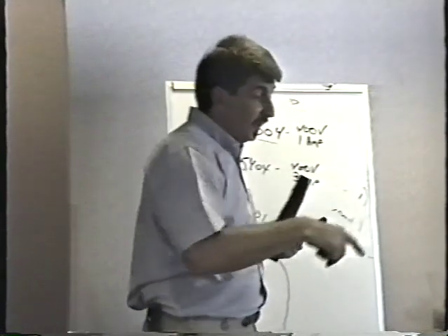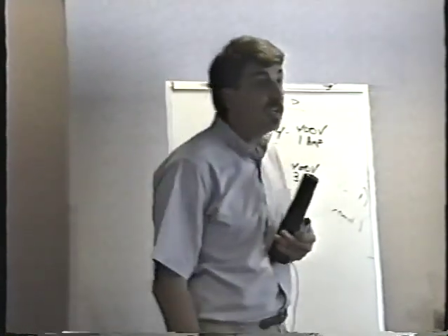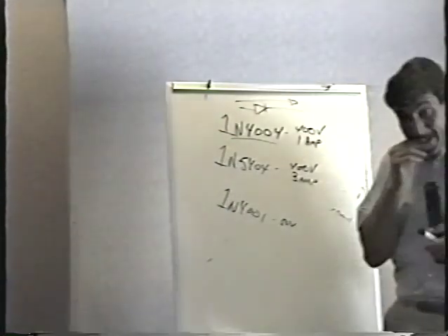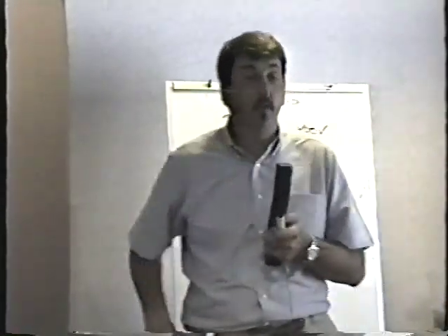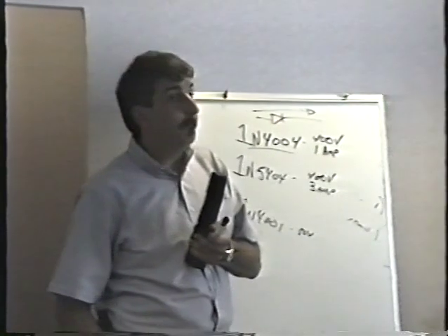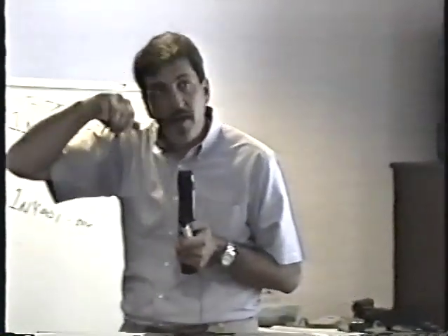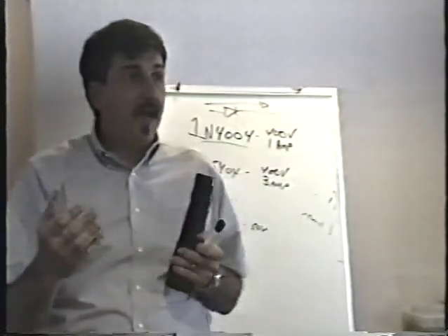In fact, if you look on the list, 1N4007s, those are 1,000 volt diodes. Those are pretty common, easy to get diodes. And in fact, the place I usually get my diodes from, they're the same price as the 4004s. And so very often I'll buy 4007s because I can use them for anything, can't I? Up to 1,000 volts.